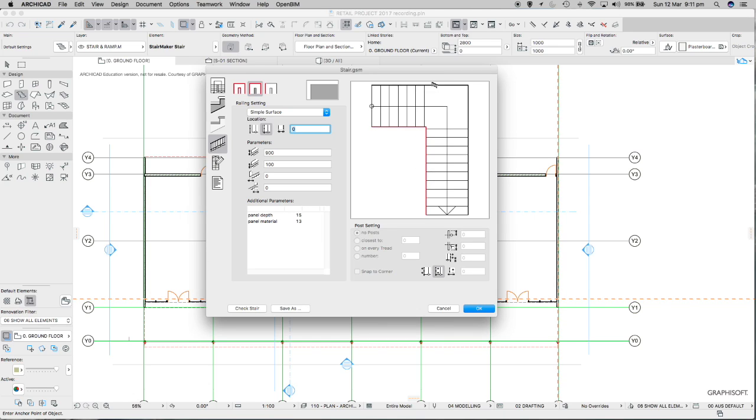But I'm going to start with this outside one. That's the railing that we want. So the railing type, we'll go to a simple bar. We just want a single handrail. This gives us an indication of the floor and then the railing up above the floor. We want it offset in by 75mm. You'll talk about that in your construction class as to why we want that in plan view offset 75mm. It gives knuckle clearance around the handrail to the wall that it's adjacent to.